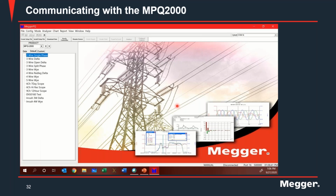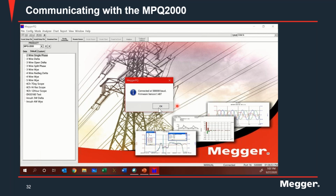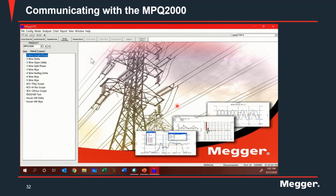Communicating with the recorder. You can establish communication between the unit and the laptop, and the way of doing that on the software is either by an Ethernet cable or through a USB cable. Here I used a USB cable, and if you look at the top right, you will see a box which says COM16. So when I connected the recorder to my laptop, it automatically detected the port number that was assigned to it, and then I can verify whether it's communicating with the unit by clicking on verify connection.